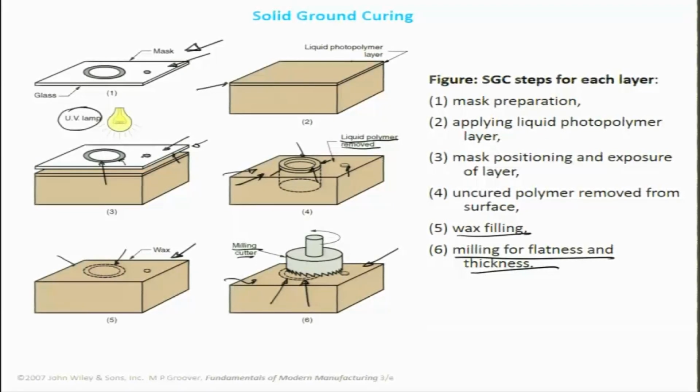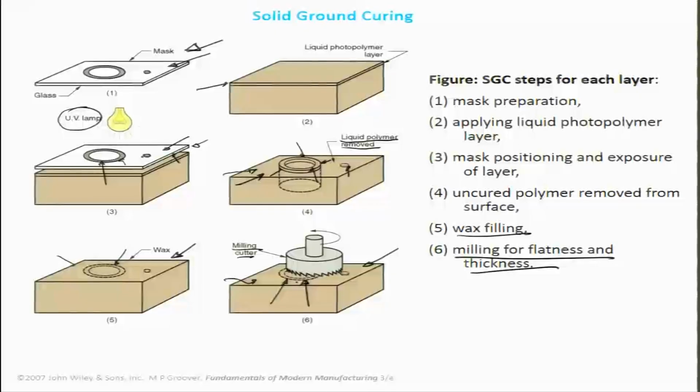through mostly an aerodynamic wiper. In this case the liquid polymer is such that whenever it's not cross-bonded to the substrate or to itself, then it is flowable enough and the viscosity is low enough for the liquid to drain off the surface. So you are draining the liquid off the surface again, thus keeping a small solid portion on the top. Again do the wax coating, again do the micromilling, and in this manner you build this particular hollow cylinder, layer by layer.